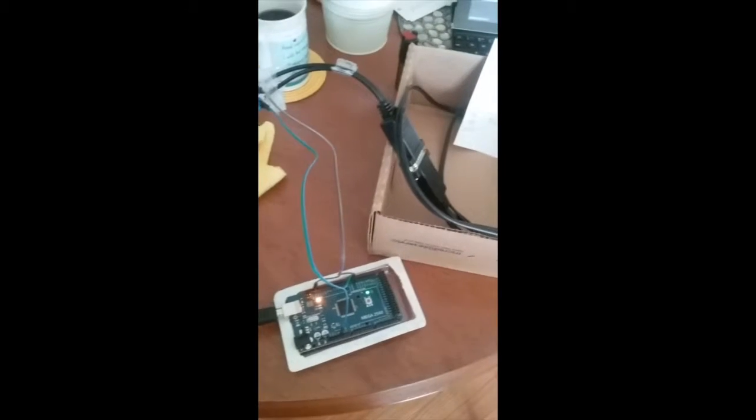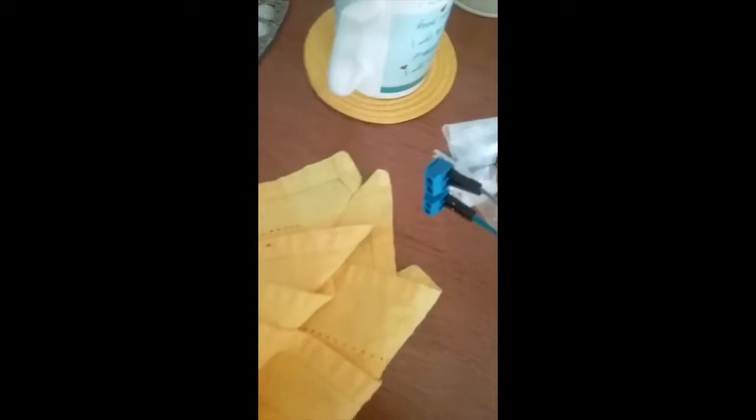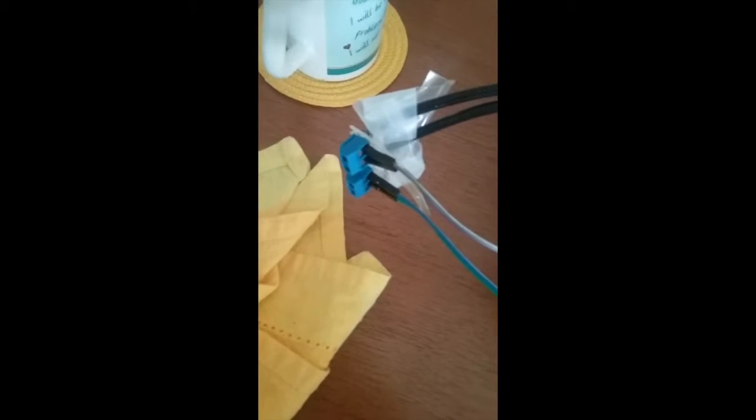Okay, what we are looking at is the first successful interfacing of an Arduino Mega through one of these cables, which is a Sound Blaster cable, where it's been clipped and the four important wires have been identified, and going into the MIDI out, going into the input of a MIDI interface to a camera connection kit to MIDI trail running on an iPad. So this is just a simple MIDI Arduino sketch that comes with every Arduino.